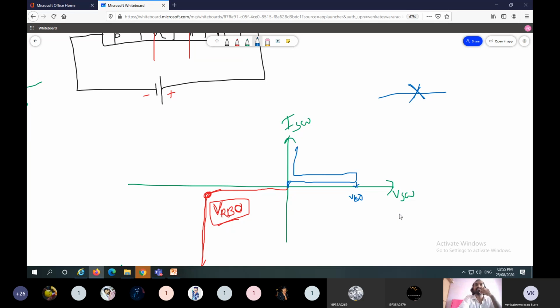So with increasing supply voltage, the voltage across the switch is constant. There is some on-state voltage of 1.5 volts. For an SCR, the voltage across the switch during on state is 1.5 volts. For a diode, it will be nearly 0.7 volts. So this constant voltage appears across the switch. With increasing Vs, IS increases, and the anode current or switch current IA increases like this.